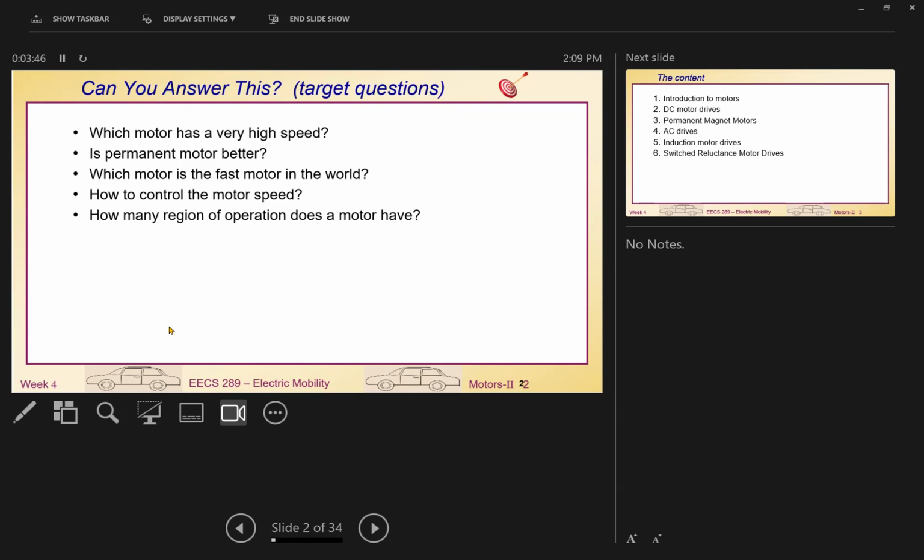So 0.5 mm to about 1 mm. You can see that it's really thin. So the alignment of the motor, the shaft alignment, is really complicated. We need to do it really well, and we need to put bearings there to make sure they align really well. So that's the thing we need to look into.